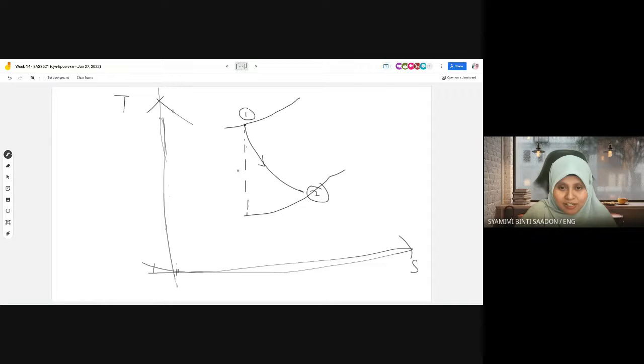Okay, so like this, the process. This is actual, this is ideal, or we call it isentropic. That's why for the ideal cycle the entropy is the same. We assume that there is no energy loss, so entropy is constant. That's why it is a vertical line, same entropy for point 1 and point 2 prime.